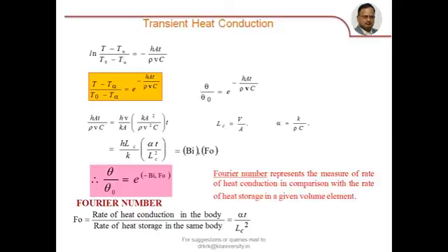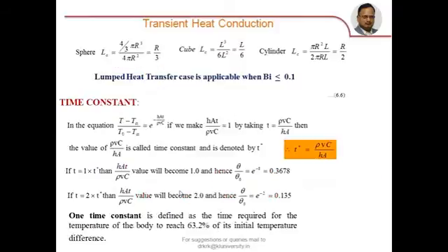So you may get a question now. If we assume a body has a lumped heat capacity system, temperature becomes independent of x, and it is only evaluated with reference to the time. And the governing equation is theta by theta naught is e power minus hAT by rho VC, which can in general be expressed as a function of Biot number and Fourier number. So throughout unsteady state conduction, you involve two non-dimensional numbers. One is Biot number and the other one is Fourier number.